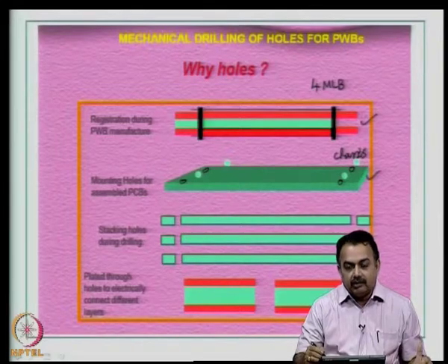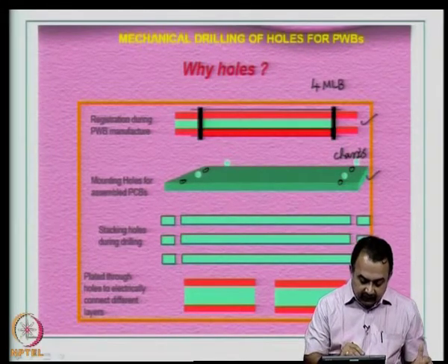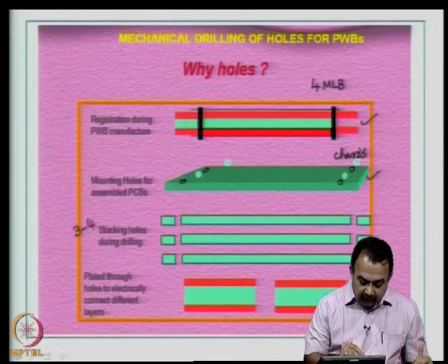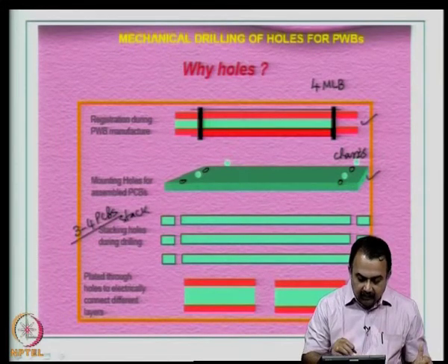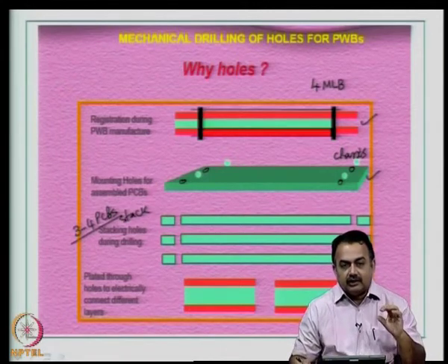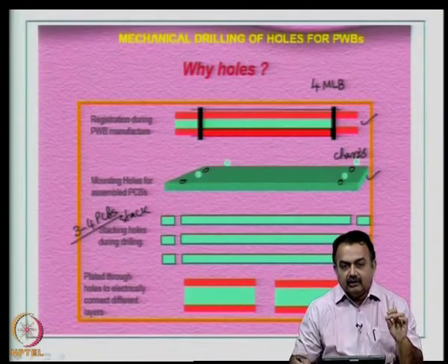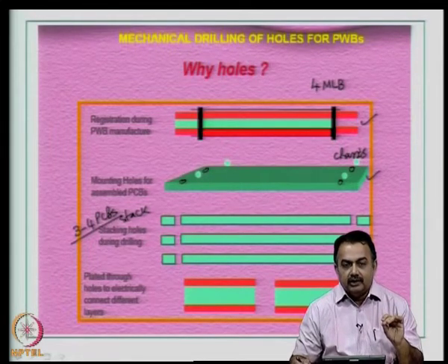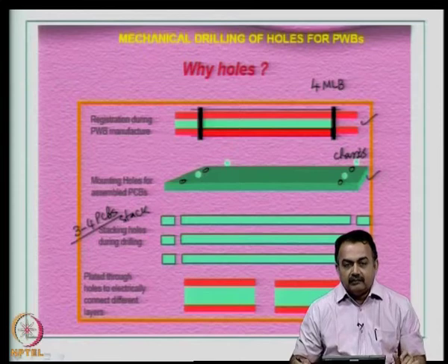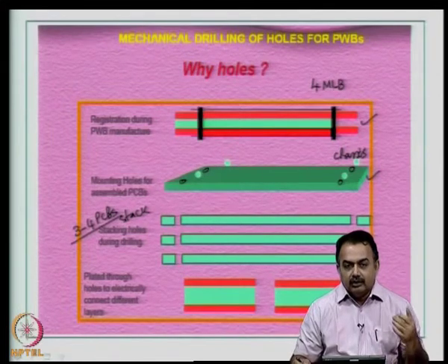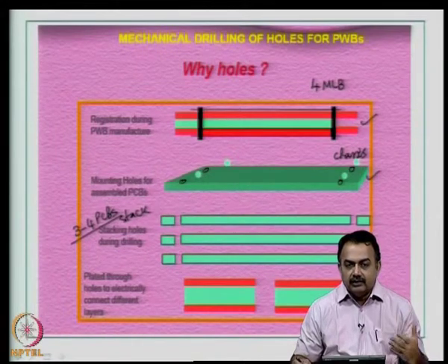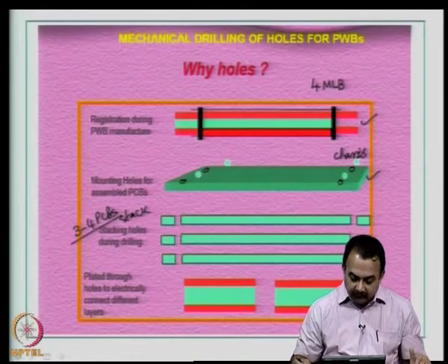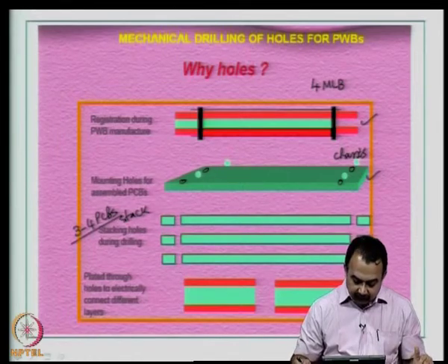Even during the drilling step, when you are stacking, let us say 3 to 4 PCBs at a time, you require all the laminate structures to be stacked perfectly, so that there is no misregistration or vibration or movement during the drilling process, because if that happens, you are going to break the drill bit, you are going to get a misregistration and you will end up with a wasted laminate structure.